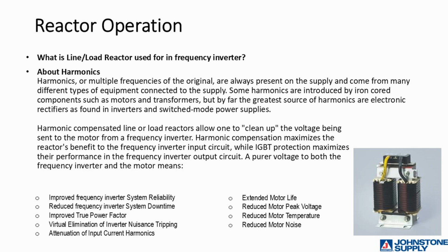So what is a reactor used for? It improves inverter system reliability, reduces inverter system downtime, improves the true power factor, allowing the inverter to run more efficiently, eliminates inverter nuisance tripping, reduces incoming current harmonics, extends motor life, reduces motor peak voltage, reduces motor temperature, reduces motor noise.